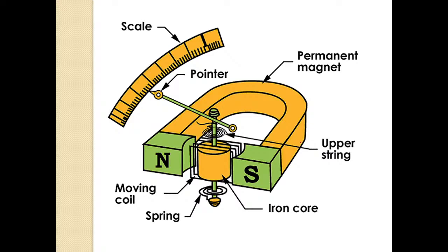That's what happens here. See here, there is a moving coil. This is the moving coil. So when current passes through the coil, depending on the current, deflecting torque is induced. When current passes through the coil and this coil is placed in the magnetic field, it will experience a force. Okay, so that image is there somewhere, the motoring action.